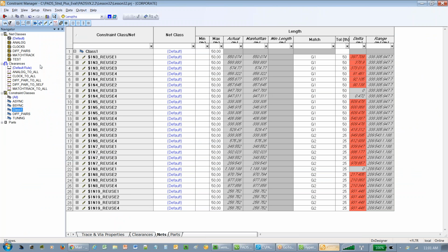All right. Now, another feature that I'm showing here that helps with the whole review process. So you as the electrical engineer, once the PCB has been started, don't know if the PCB designer has actually followed your design rules. You're hoping they're doing the right thing and using their DRCs to do so. Why shouldn't you be able to see all of the length information based on what they're doing? And you can do this at any time.